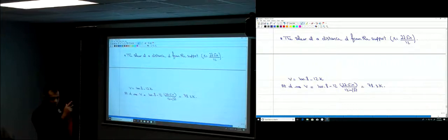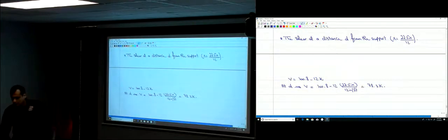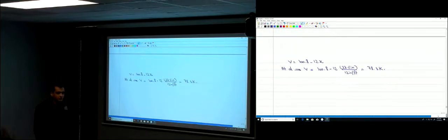You started at 100.8 and at the middle you ended at 0. Here you ended at 16.8, so the slope is less. So for 78.3, you might need a smaller spacing for the stirrups, right? In the previous problem, the spacing was 5 inches at the beginning. Now you might need a smaller spacing.